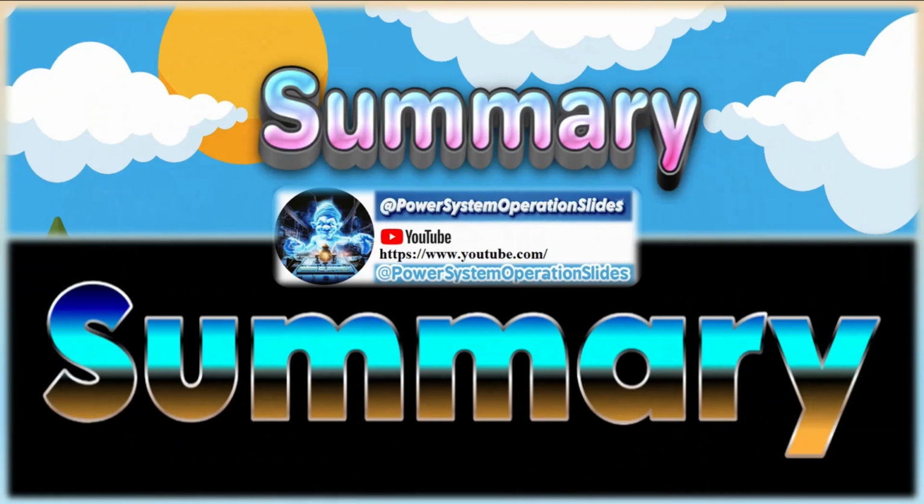Phase under voltage release criterion: the busbar protection tripping command is released by under voltage function. The under voltage function senses voltage collapse during short circuit on a busbar. In case of current transformer circuit failure in a bay, the missing current will cause differential current in the measuring element and it can cause unwanted trip of this busbar section. In order to avoid this faulty trip, the measuring element can trip the busbar section if the under voltage release criterion is fulfilled.